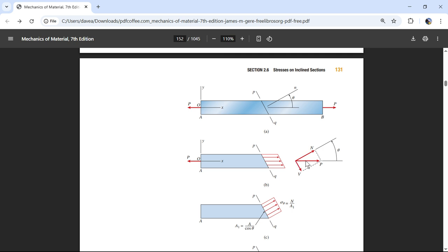So now if this force is 100 newtons, I'm going to have 70.7 newtons in shear, and 70.7 newtons in tension. But we said that the material, steel, can take a huge amount of tension. So just the fact that we're only getting 70%, that's actually stronger in tension at this angle.